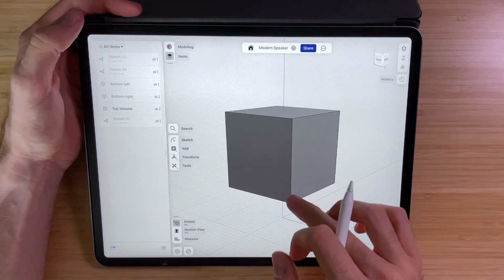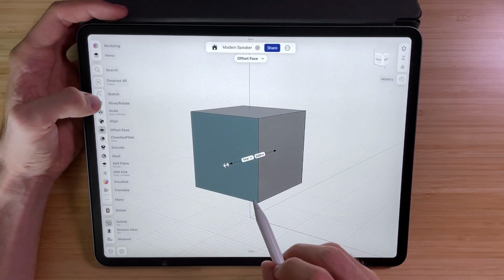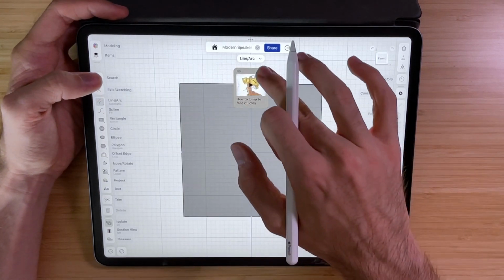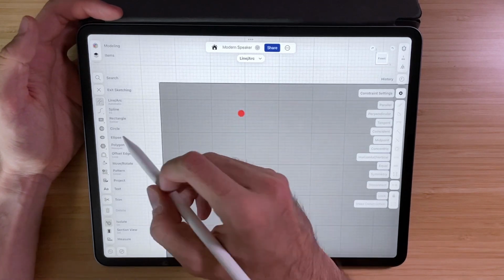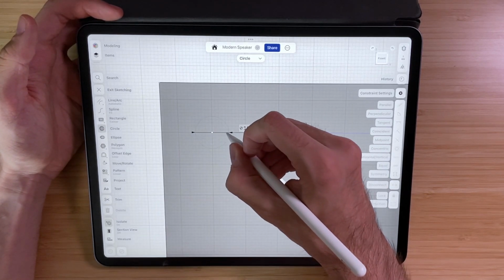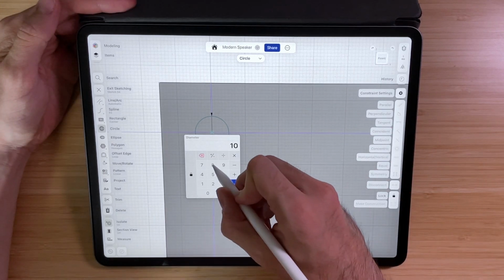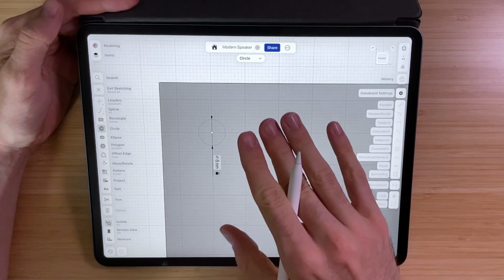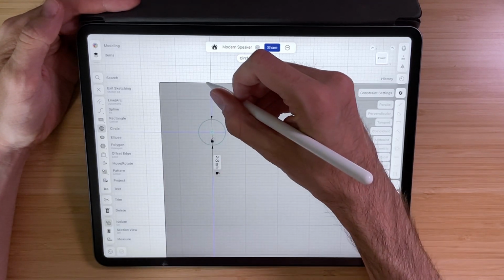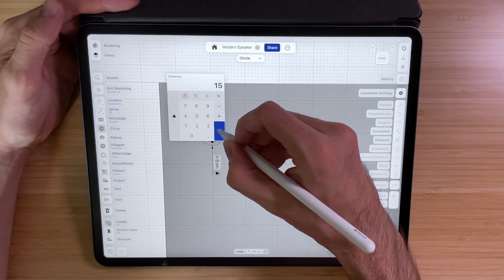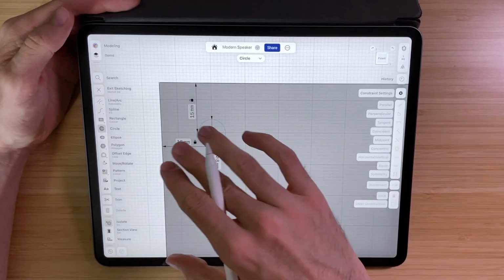So now that we are in the isolate mode, we can select our front surface and then start our sketch for the pattern. So let us move towards the upper left side and then create our first circle. Select our diameter, and we can change that later on. So let's just set it at 8. And also we want to constrain it to the top left side. So let's constrain the top dimension and also this distance to 15.